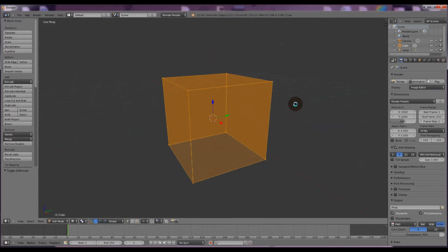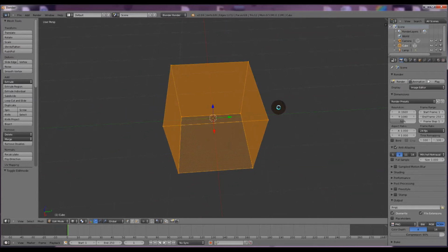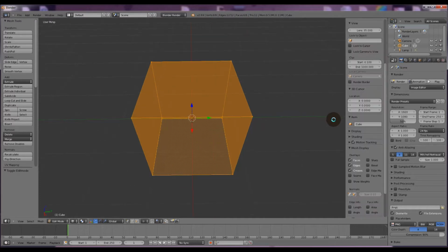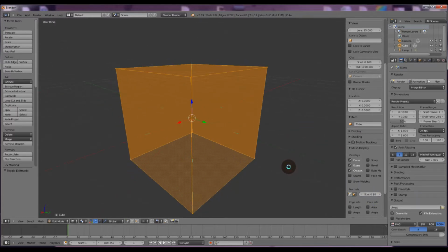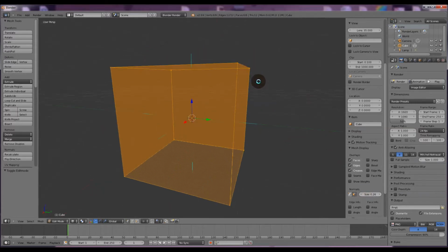It's called a UV, nothing to do with ultraviolet light or anything like that. When we're moving an object in 3D space, as we've talked about before, you can move it in the X, Y and Z axes. But to describe the surface, they use U, V and W. U's across, V's up, and W represents the normal. A normal is a way of identifying which way around a surface is facing. And these little blue lines here indicate the direction of the normals.